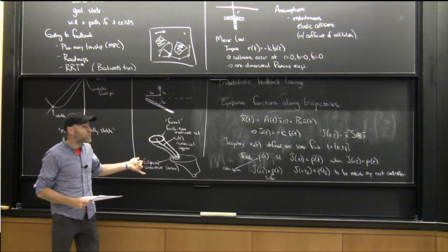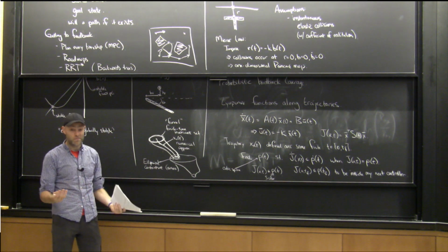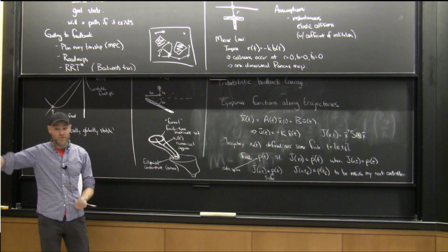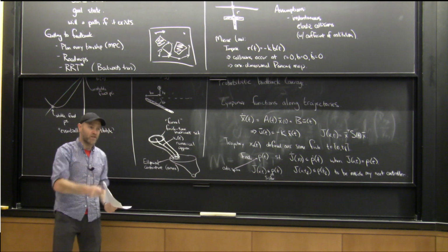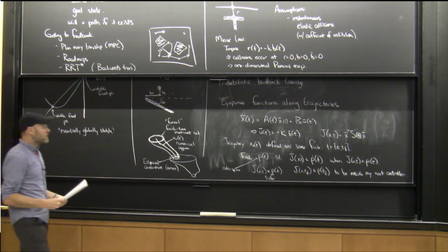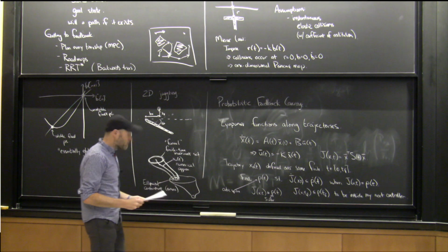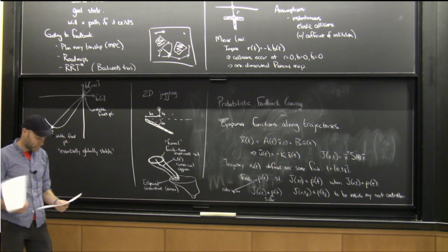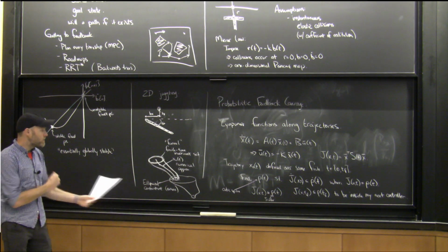Okay, so that's sort of the best recipe I can give now for things like acrobots and cart-poles. It sort of pulls together all the pieces that we've talked about from trajectory optimization and sums of squares and randomized motion planning. And it does, I think, give relatively strong tools for probabilistic feedback coverage, okay? There's a few more details that maybe are worth mentioning.